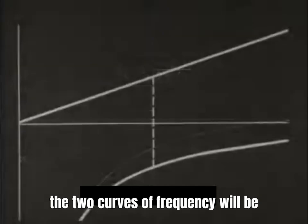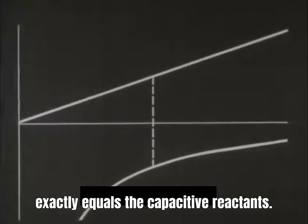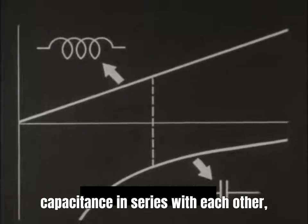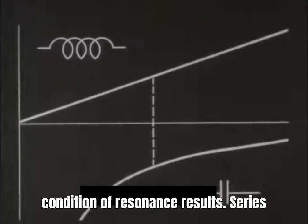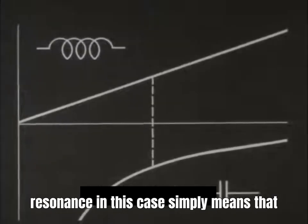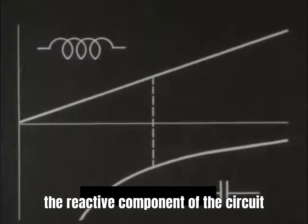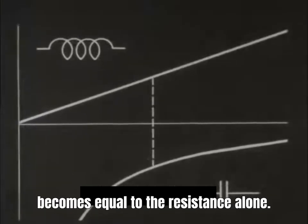By combining the two curves, a frequency will be found at which the inductive reactance exactly equals the capacitive reactance. When this occurs with the inductance and capacitance in series with each other, the two balance each other, and a condition of resonance results. Series resonance, in this case, simply means that the reactive component of the circuit ceases to exist and the total impedance becomes equal to the resistance alone.